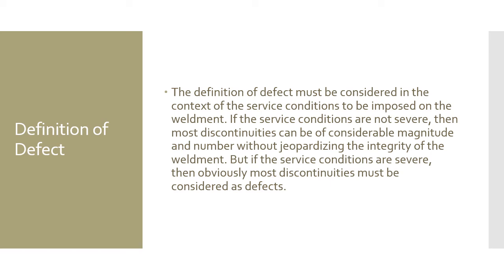A weld on a bridge might have a defect that would not be a defect on HVAC, heating, ventilation, and air conditioning. You might have two totally different acceptance criteria. The acceptance criteria is going to set the boundaries of what's a defect and what is not. With stringent things like aerospace and nuclear power, there are defects you might reject due to their acceptance criteria.